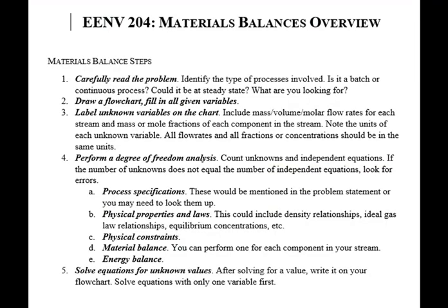First, I want to review the steps you should be taking every time you see a situation that might require a mass balance. If you're in school, definitely read the problem. For some reason, a lot of engineers don't like doing this, but you have to do it, and you have to do it carefully. When you do this, think about the problem. Is it batch, continuous, steady state, transient? What sort of things are you looking for?